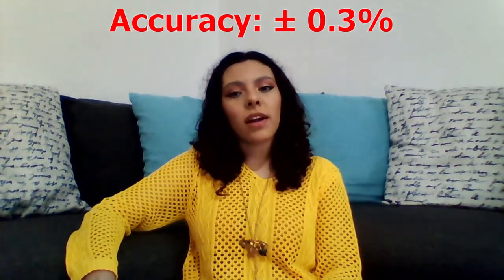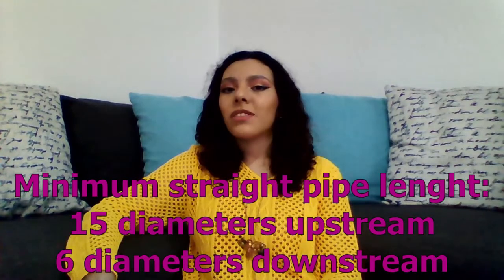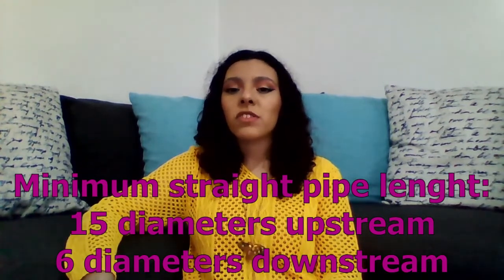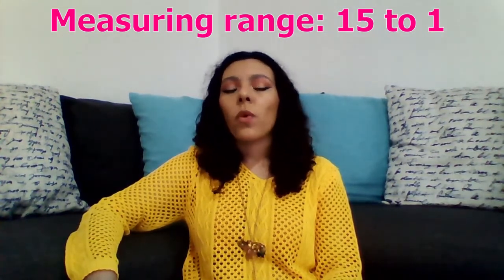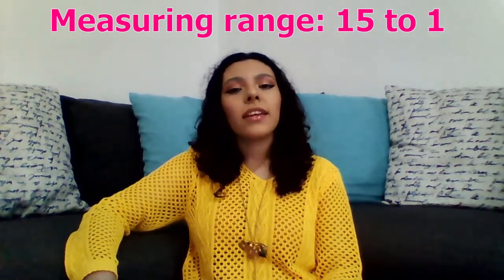The accuracy is very high, of the order of plus minus 0.3%. Maximum precision is achieved with a laminar regime by installing the instrument at a minimum of 15 diameters of straight pipe upstream and 6 diameters downstream. The measuring range goes up to the 15:1 ratio between the maximum and minimum flow and has a linear scale.